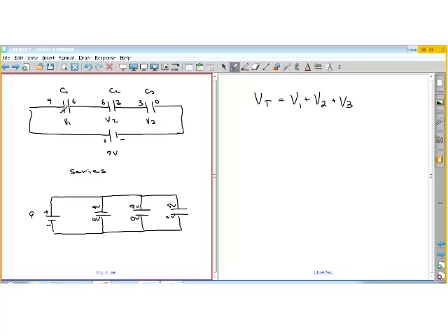What happens is that this plate becomes positively charged. This plate becomes negatively charged. To get the electrons, they take them from the plate that's to the right. So the electrons from here push into the wire, and the ones in the wire are pushed out onto the plate. Likewise here, the same thing happens. You've got electrons on the other side, you have the lack of electrons here, and they just moved. They can't cross because there's not a complete circuit. Current never goes, electrons never cross this boundary because it's a gap. So all we can do is move electrons around within the system.